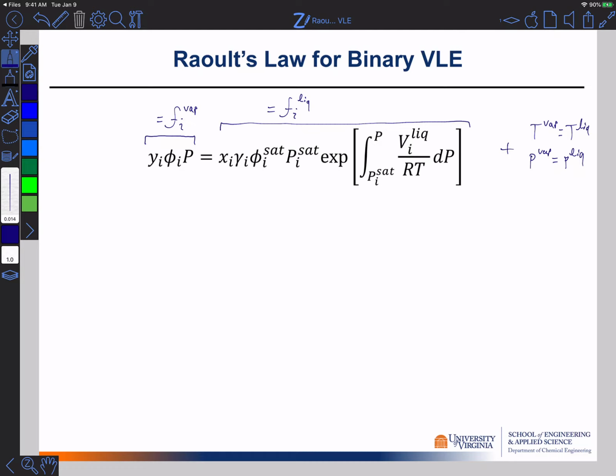All right, and we said that this expression, this expansion for the fugacities of the vapor and liquid phases that we have on the screen, is going to work well for us so long as we aren't above the critical point. Basically, so long as there's a numerical value of the saturation vapor pressure for the particular component we're interested in at the system temperature we're operating at. So that's one of the limitations that comes up in this most general result. But we don't need any assumptions to get here. We just need to have values to actually plug in. And so we're never going to go wrong by starting at this particular place.